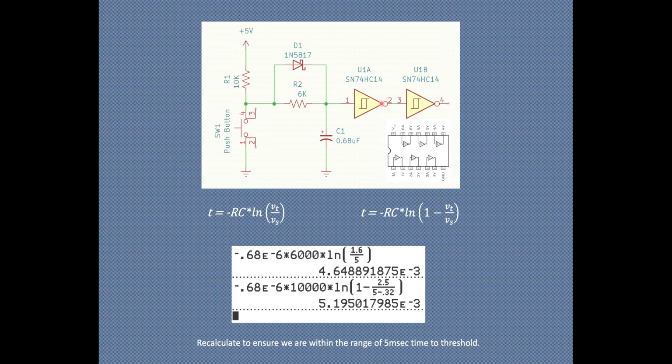And we've got back-to-back Schmitt triggers because we want the input, if the input's high, we want the output to be high also. We don't want it inverted. If you just use one, it's high here, low here. And these are in the same package, so it's fairly easy. You put your input on 1, take your output off 4, and put a jumper between 2 and 3.